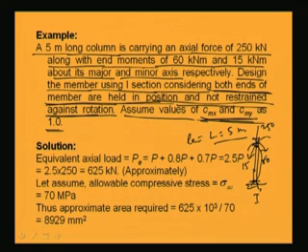effective length, right. So, first what we will do, as we told, first we can find out some equivalent axial load. Equivalent axial load will be say P plus, I do not know what will be the value due to moment. Say we are increasing 80% due to Mx and say 70% due to My. Just approximately we are trying to find out some equivalent load, because we cannot find out equivalent load unless we know the section. One approximate section has to be known from which I can find out A by Z ratio. Okay. Unless I know A by Z ratio, I cannot find out the equivalent load.